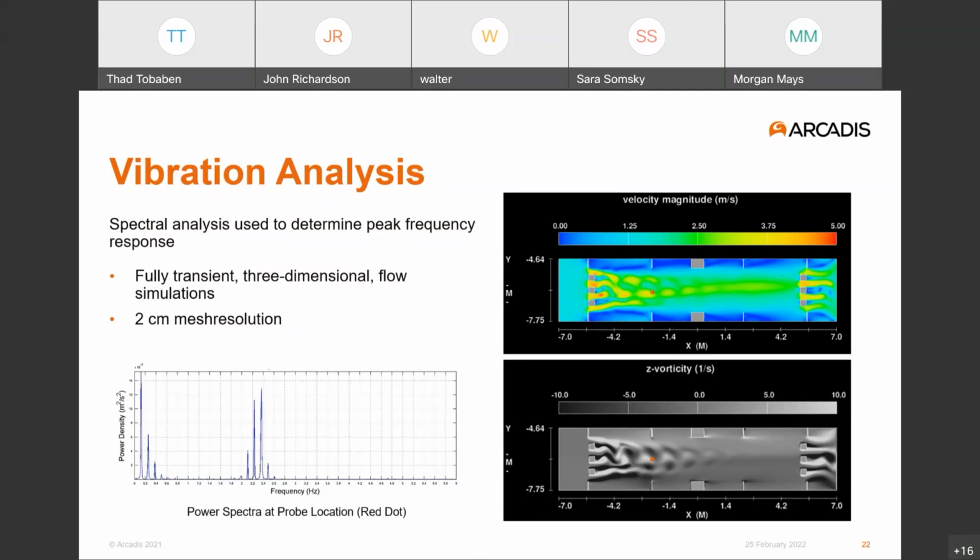So we see, to the left of the figure, disturbances at a lower frequency, and then the frequency gets a bit higher. We have another peak, and then what's not shown is the good news, and that is that what we wanted to avoid were frequencies, if my memory serves me correctly, on the order of 50 or 60 hertz. So these disturbances were well away from where we wanted to be. So that box was checked, so to speak.